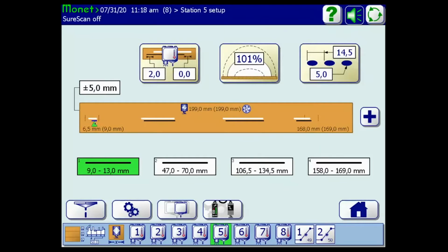It probably turned blue. Mine turned blue. I don't know if you could see that first event here. Because that event is so short, even though I programmed it as a line event, the software is smart enough to know that it's going to use a spot mode on that first event. So that's why sometimes you'll see very short line events turn blue when you increase the speed.